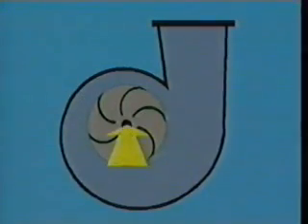Gas enters the compressor through the suction port and is directed to the center of the impeller. As the impeller rotates, the gas rotates with it. This circular motion generates the forces that lift and move the gas away from the center of the impeller, as well as creating a suction at the center of the impeller.